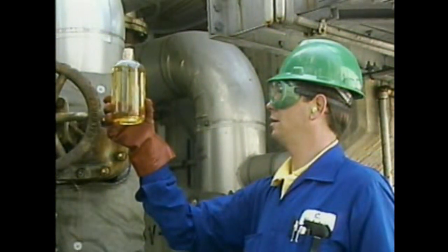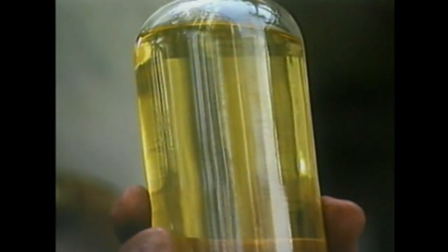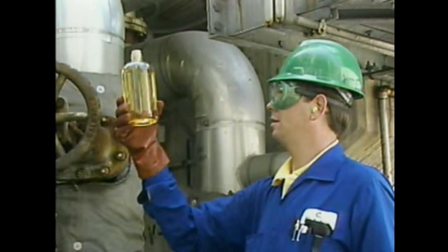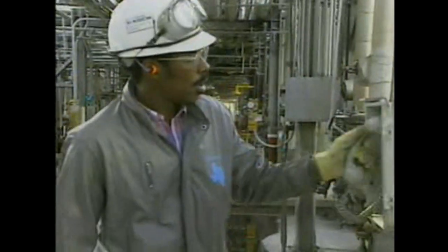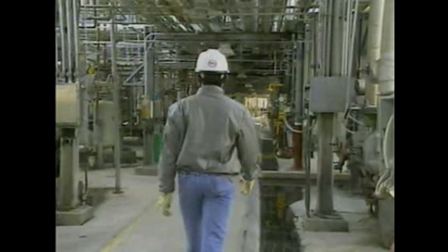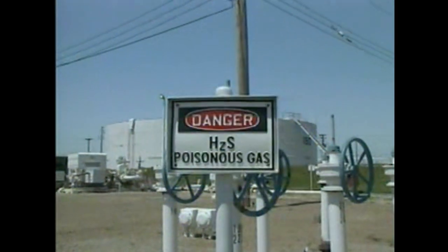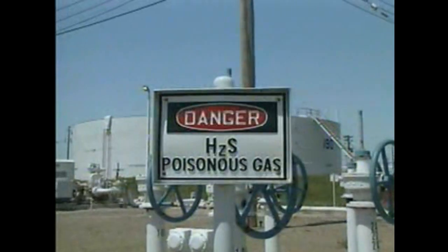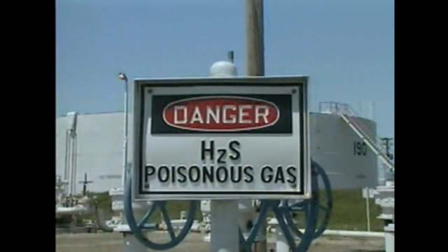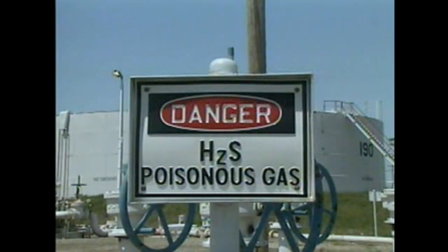One property that can indicate a problem is the chemical's appearance. If a substance has changed in color or density, or if it looks abnormal in any other way, do not handle the substance. Follow your company's procedure to report the condition and determine why the change occurred. Like appearance, odor is a basic physical property that may help identify a hazardous situation. Many chemicals have characteristic odors, such as hydrogen sulfide, for example.